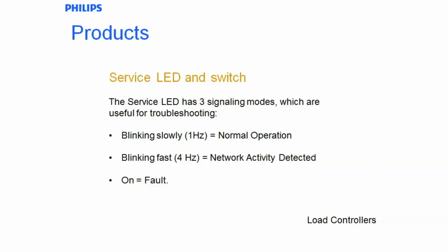One of the more important functions on an enumerated Dali controller, if you do 4 pushes, it does what we call a 15-minute Dali broadcast walk test sequence. This is a very useful function for contractors to ensure that they have Dali connectivity to all of their fittings. Once the whole system is wired up, they can press the button 4 times and then through a period of 15 minutes, the lights will cycle between 100%, 80%, 60%, 40%, 20% and off. This enables the contractor to walk around and make sure that he has got Dali connectivity to every luminaire.